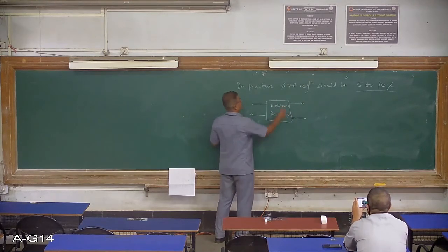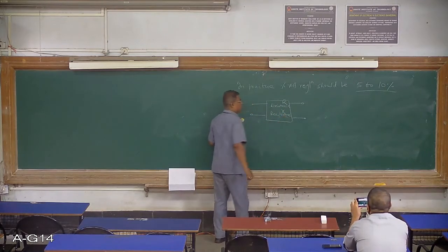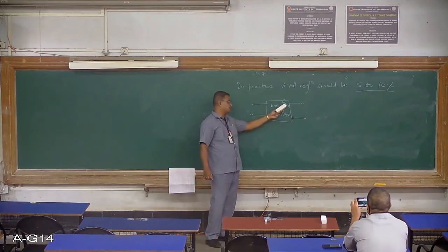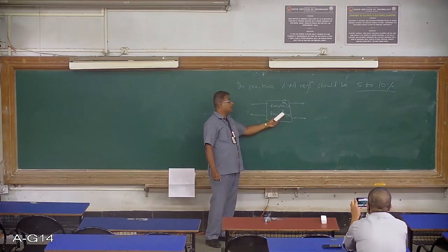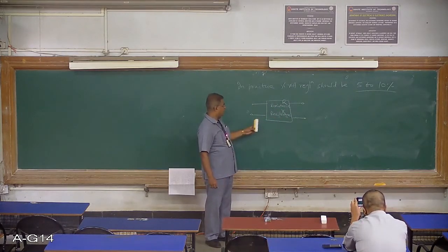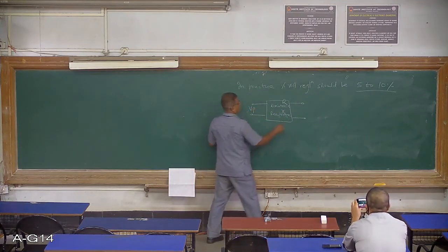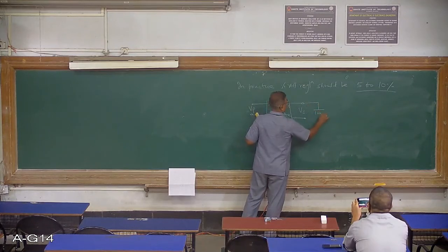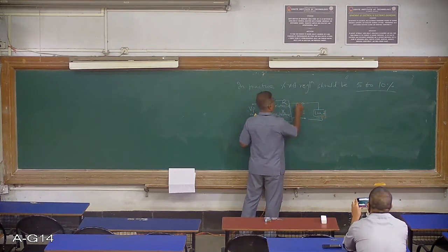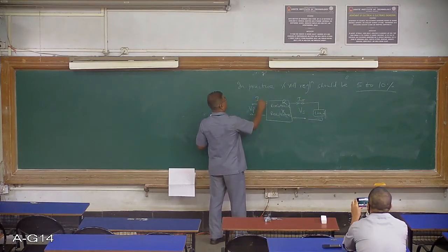Resistance is R and leakage reactance let us indicate by X or XL. So there are two parameters in the primary and secondary winding, that is resistance and inductive reactance. So whenever the transformer is loaded, supply is given, secondary voltage appears, and load is connected, you will find the flow of current, secondary current IS and primary current IP.